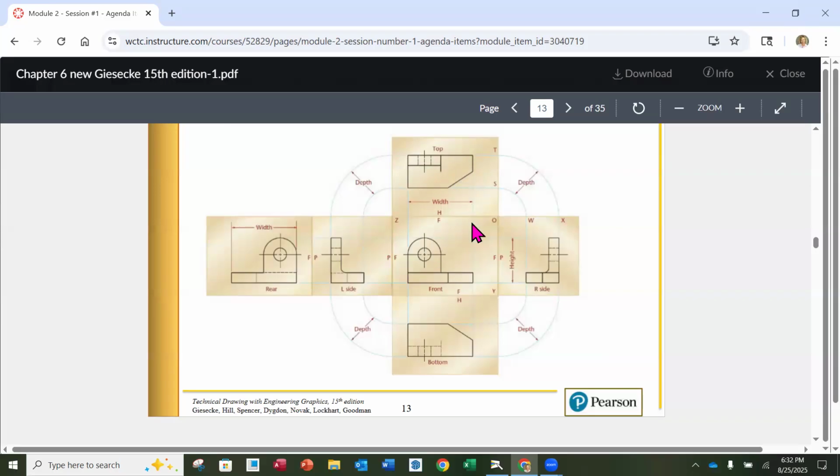The right edge of that part is in line. Orthographic, it has to be that way. You can't have it shifted left or right. When we create multi-view drawings, they have to be in line across the views, all of them. And that's what makes it easier to understand what different elements are too.